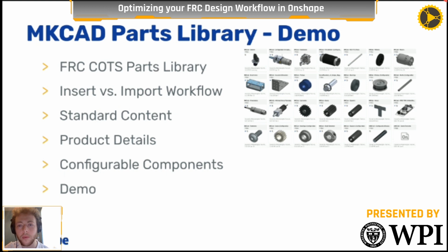That's especially common with configurable versaplanetaries, which is up here, but it looks a little broken. I bet that it does work in real life though. Configurable versaplanetaries, that's a common thing that teams are swapping out. Maybe they want to add an encoder stage, or they want to change 7 to 1 to 3 to 1 or whatever. That's configurable. So rather than setting up your entire versaplanetary model again, on the back end within the MKCAD studio, it's handling all of that. So with a couple clicks, you can just flip it and do all of that stuff.